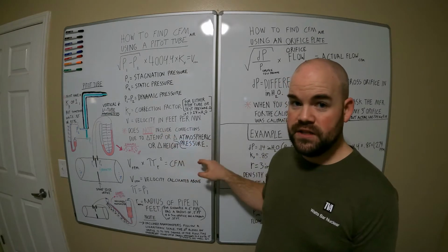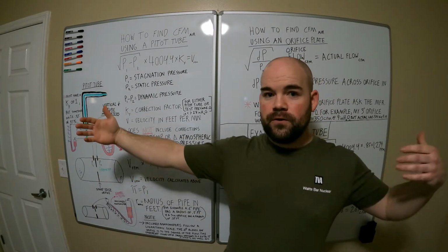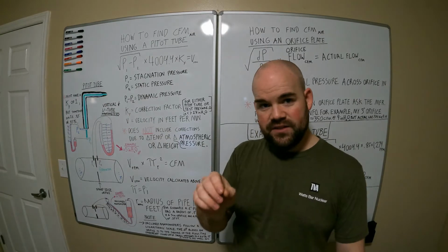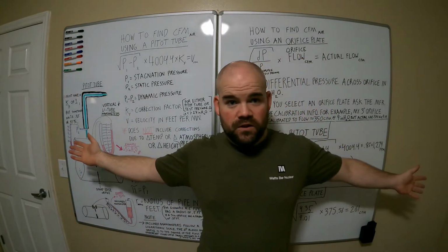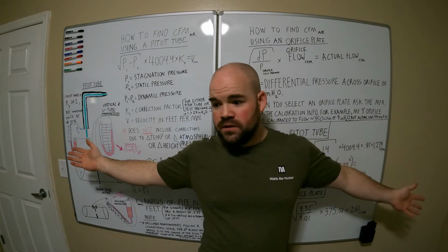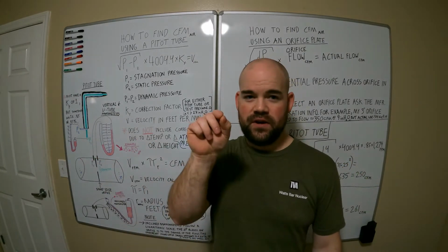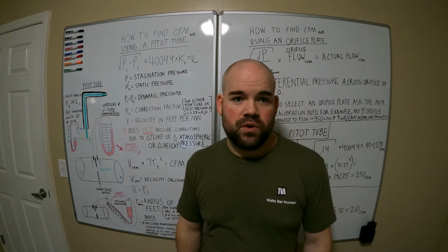Now, if you want it to raise 10 inches over a very far period, the further you make that scale 10 inches up, the longer you make it, the easier it's going to be to see those changes. Some people have 10-foot long manometers. You can definitely do that, and it makes it a lot easier to see those very minute changes. And you can probably do it all for 20 bucks worth of parts at Lowe's.